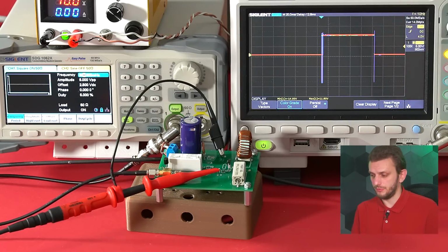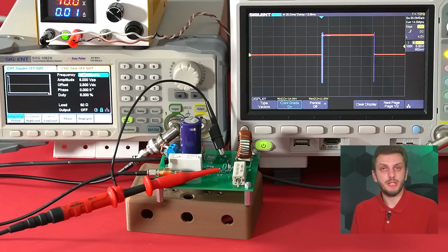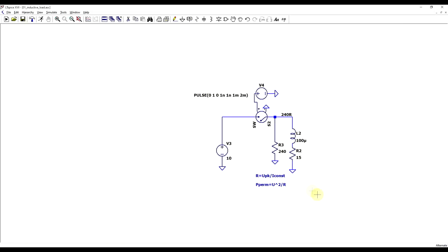So although this sort of diode is usually more expensive than a varistor, the TVS is far more precise and predictable in its behavior, and at the same time can be built to have lower junction capacitance. So when the exact clamping voltage threshold is critical, like in low voltage systems, or when you need very low added parallel capacitance, like when protecting communication lines, the TVS type of diode is usually better suited than a varistor as a protection element. Next, we can look at resistor and resistor capacitor networks,